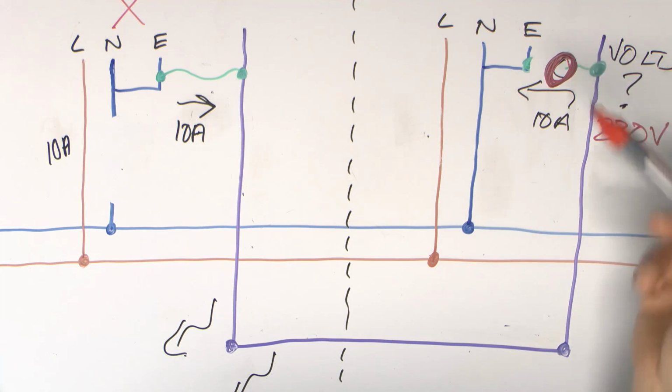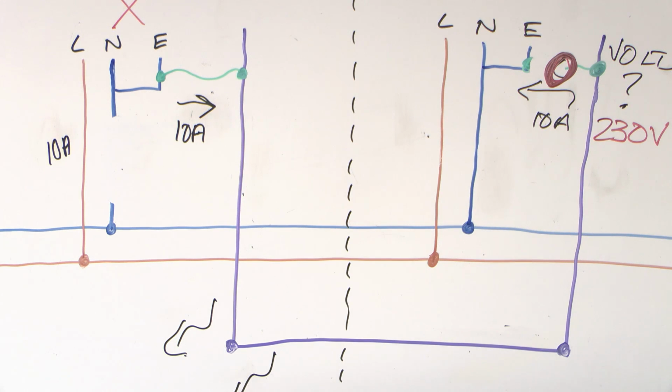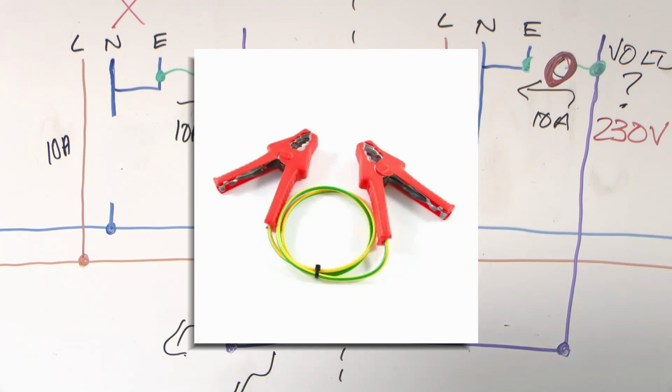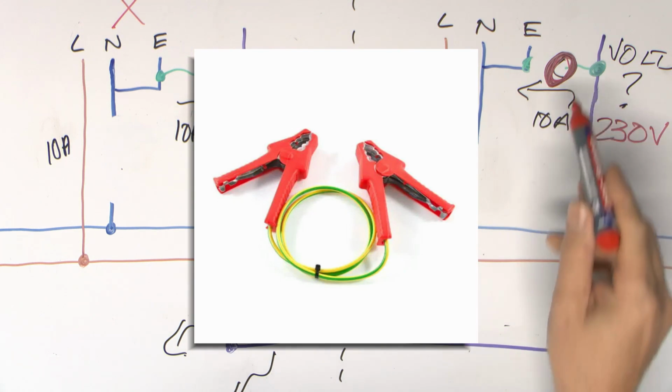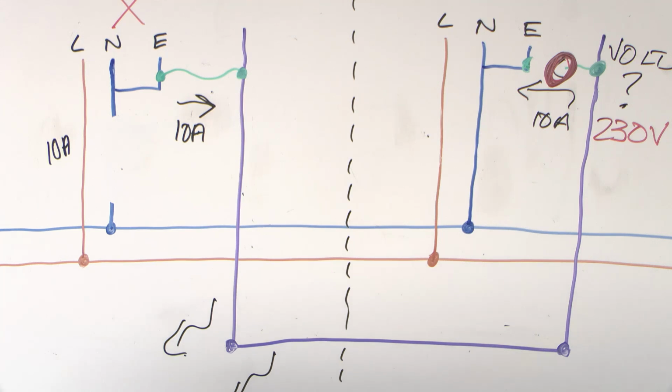If this happened to be a gas pipe and you're working on the gas meter, then there's going to be a chance of igniting any stray gas there. So that is why gas people have those sort of jump lead type affairs where you can clip onto the two sides before disconnecting it. Bearing in mind that can happen in normal operation as well.